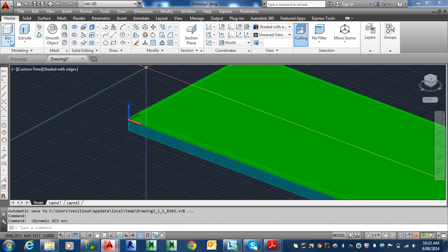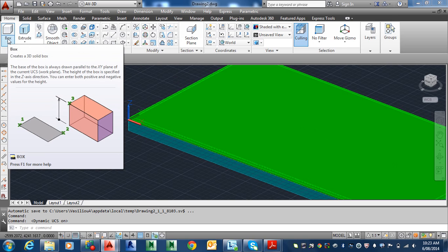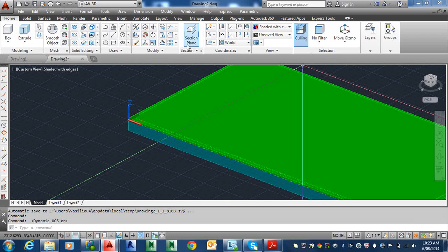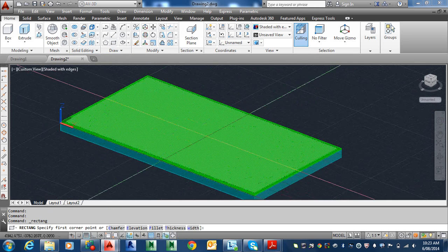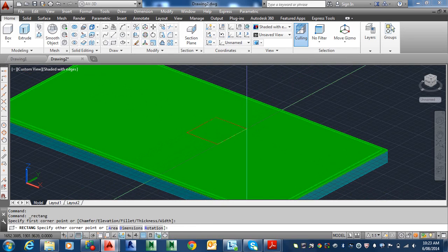So when I start drawing a rectangle, how big is that set down? It's 6 meters by 3 meters by 50 deep, approximately where it's showing. So we can just draw somewhere on there to start with. You could draw a box and then subtract that from there, but let's try our snazzy command, press pull, which means we have to create a rectangle on top first. It detects that surface, so I'll be drawing on that surface. See that? I'm just going to put it anywhere, then move it by eye where I want it to go.